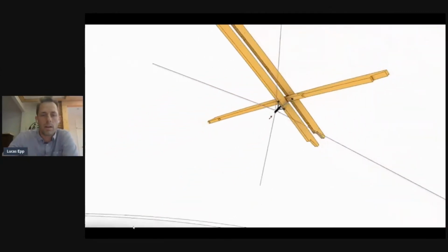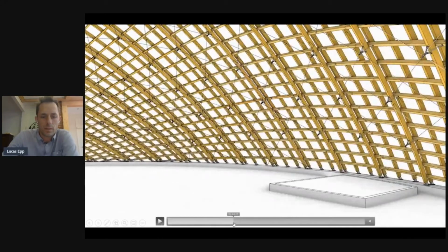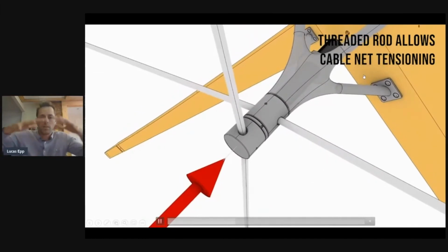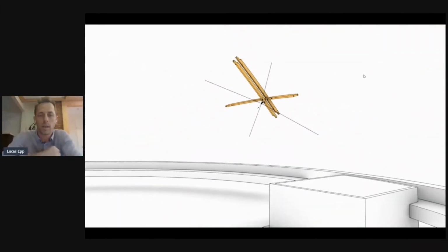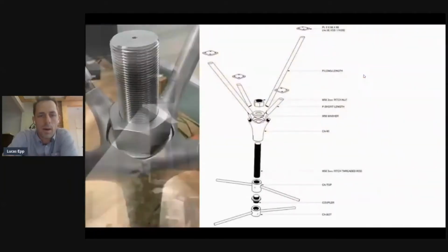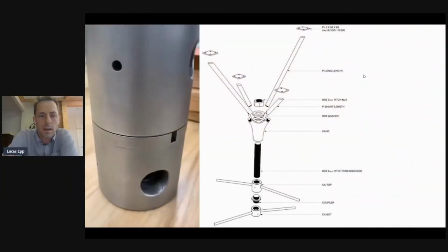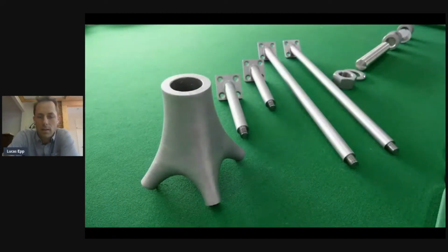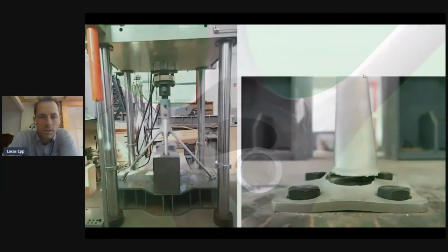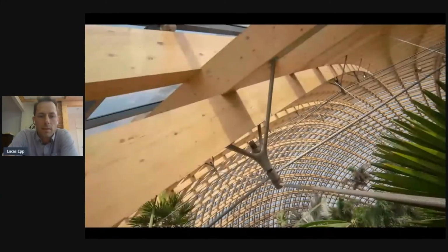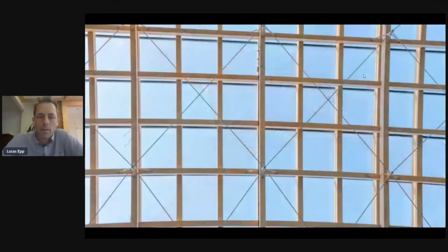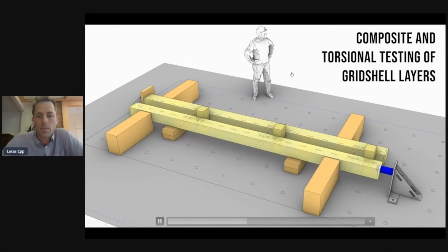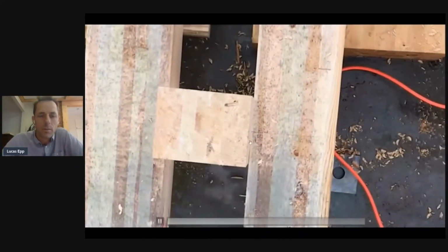And then the step you just saw there, I'll just rewind to that, where the castings are getting pulled closer to the grid shell above, actually induces tension into the entire cable net, so it lengthens all the cables. Once you come up with these concepts of these castings, you want to put them in place across the whole grid shell, so you have to use a computational design approach. You've got to use Grasshopper, you've got to use C# coding. That's been a real driver for us in creating these structures: having to create these computational approaches for these larger scale freeform structures.